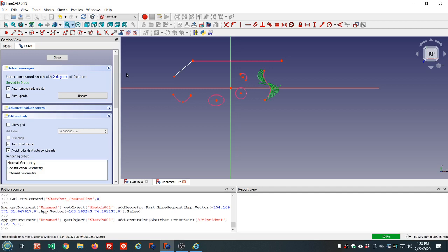For example, a cube. We might want to center a circle on the face of a cube, so we can cut a hole in the cube, and we could create external links to the four corners of that face, and then constrain our circle to the center using those four corners.